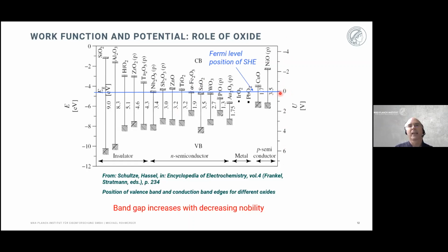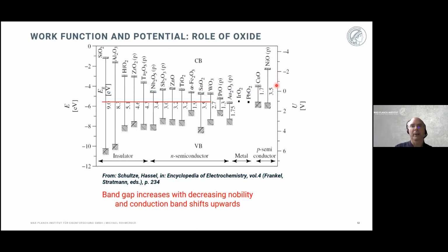0 millivolt. And that's what we usually roughly measure if we take a Kelvin probe and position it over the surface of a freshly polished iron. For zinc, we would measure more negative potential. You can see why, because that is located higher, roughly minus 400 or something like that. Yeah. What's also interesting is for most of these N-type semiconductors, the mid position of the band gap is about in the same position.